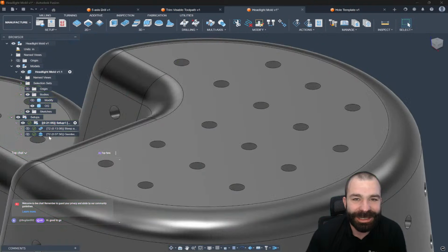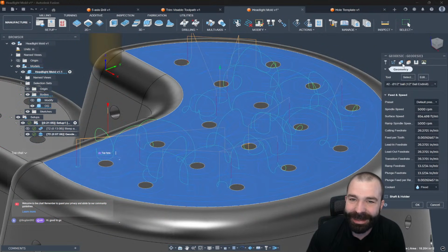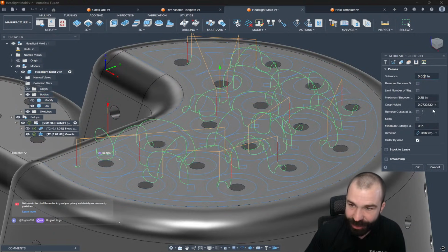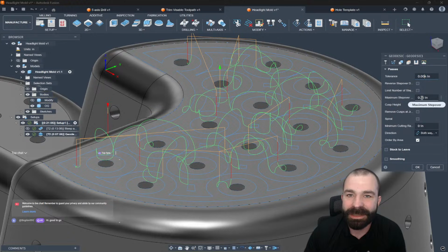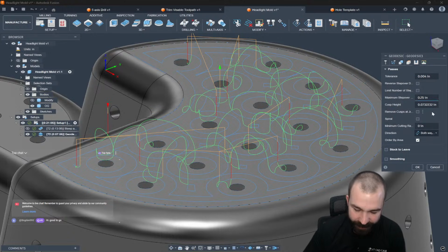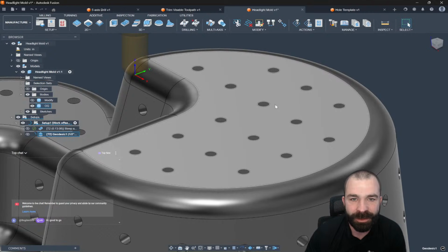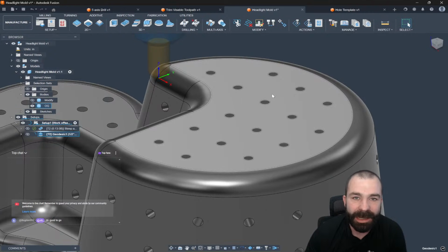And as you're seeing, geodesic is one of those toolpaths that I love, but I also have a hate relationship with, because as you're seeing, it's doing a scallop. However, it's basing everything off of a machining boundary. We could, of course, go circle at center. I am going to use my famous trick of upping my tolerance to get faster calculation. And let's go ahead and give it a little bit more of a step over so we can see more features.